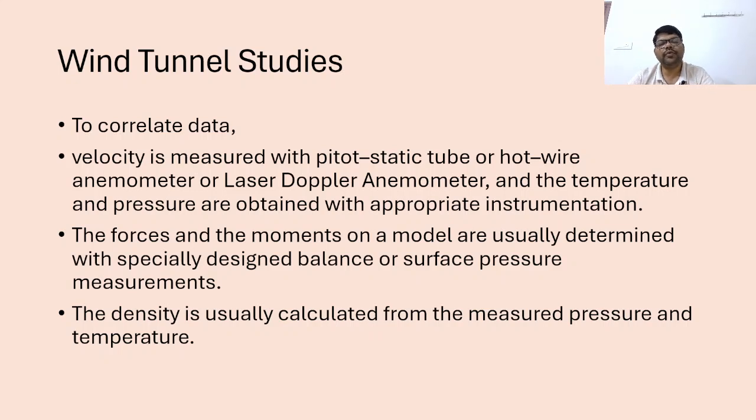Similarly, we can use surface pressure tappings or pressure transducers for the measurement of pressure, and appropriate instruments for the measurement of temperature. Once the pressure and temperature are measured, they can be used for the determination of density.